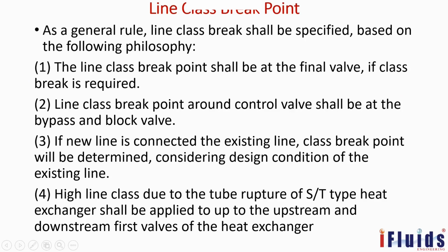So, line class break point. As a general rule, line class break shall be specified based on the following philosophy. There are 5 to 6 philosophies. One by one we will discuss. The line class break point shall be at the final valve if class break is required. We should include all the isolation valves and main control valve.